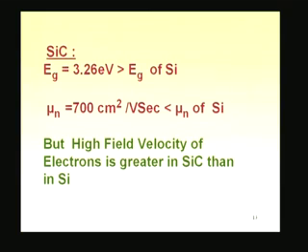But the interesting part is, ultimately what you would like to look at is this; it will tell you about the low field velocity, as you increase the electric field, how the velocity is changing. That will be smaller. That will decide, of course, the on resistance. We discussed on resistance, which is inversely proportional to the mobility and directly proportional to channel length.